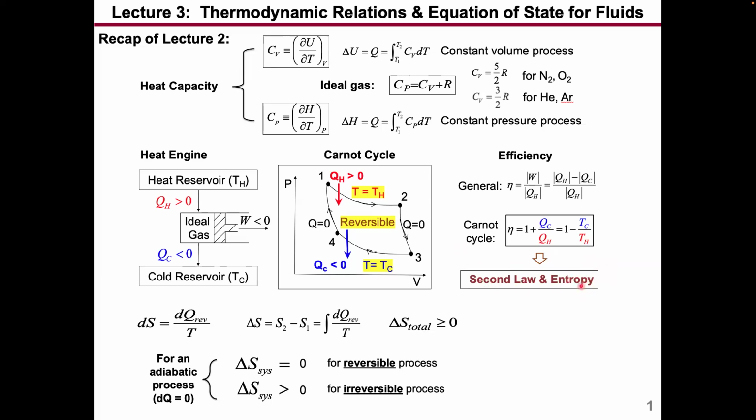Okay. And then alternatively, we can also state the second law of thermodynamics in terms of entropy. Entropy tends to increase, and basically heat always spontaneously flows from hot to cold, not the other way around. By definition, dS, where S is entropy, is equal to dq divided by T. Remember, this q has to be reversible heat, right?